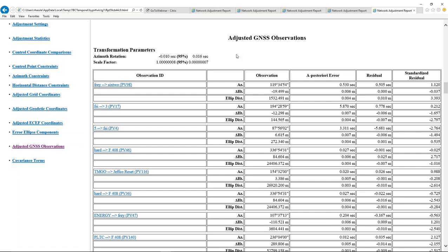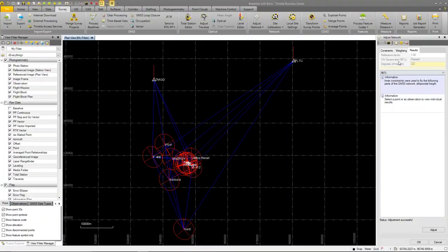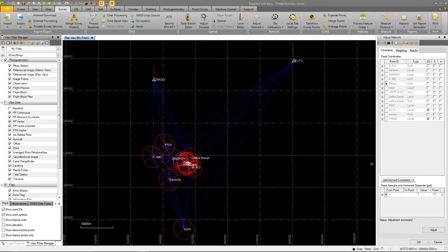I won't get one set of parameters that makes everything perfectly fit. What I'm going to have to do is start distorting my network a little bit, bending the vectors or moving them around to make it fit with all 3 points. So it'll do that in a way that provides the minimum amount of adjustment to my vectors in the network to make them fit with the points. Okay, so I'll continue on with my adjustment quickly and show you what happens when I start constraining vertically.